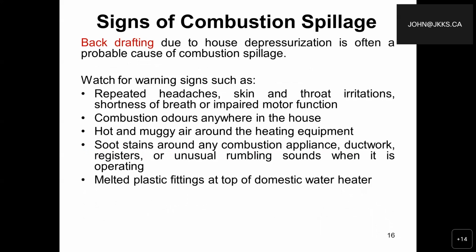Typically, some of the things I would look for is, for example, if we were to show you a picture of a hot water tank, I look for signs of little metal, we'll call it, looks like little pellets or dust sitting on top of the water heater. Signs that backdrafting has occurred. Sometimes even with furnace equipment, we can see that in the forced air heating equipment as being part of the air that was pushed back in, combustion spillage, which was supposed to be flue gases. They should have gone up, but came back.